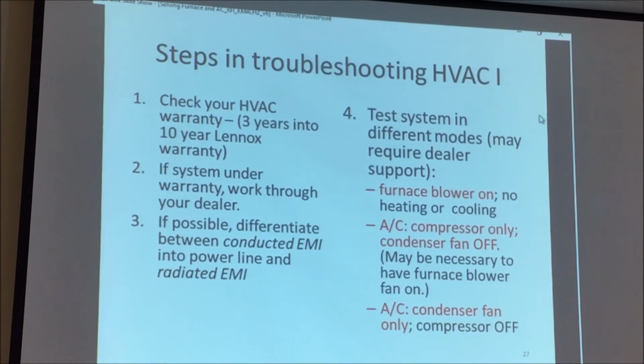Then he turned the AC compressor on, but kept the condenser fan off. I thought the condenser fan with this big propeller was the problem, but actually it turned out that the AC compressor, the motor driving it, was the source of all the RFI, and not the motor driving the condenser.